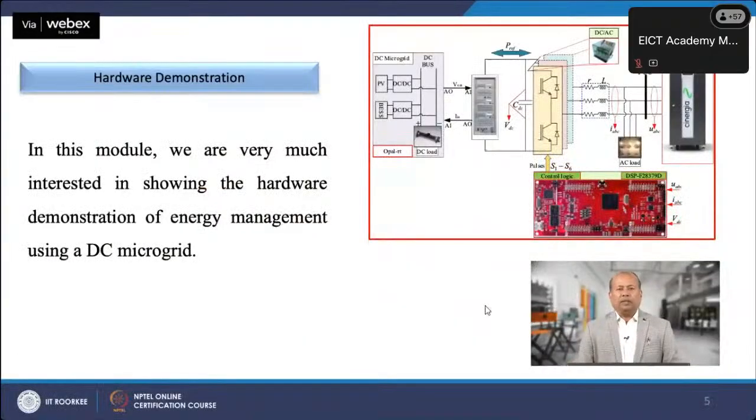After the configuration, the ADC pins must be configured to get physical signals into the DSP controller. Make sure that the ADC pin configured inside Simulink is the same as the pin the signal needs to connect to. The control system processes the signals and generates modulation signals, which are used to generate PWM signals. These PWM pins need to be configured to take them out from the DSP board.